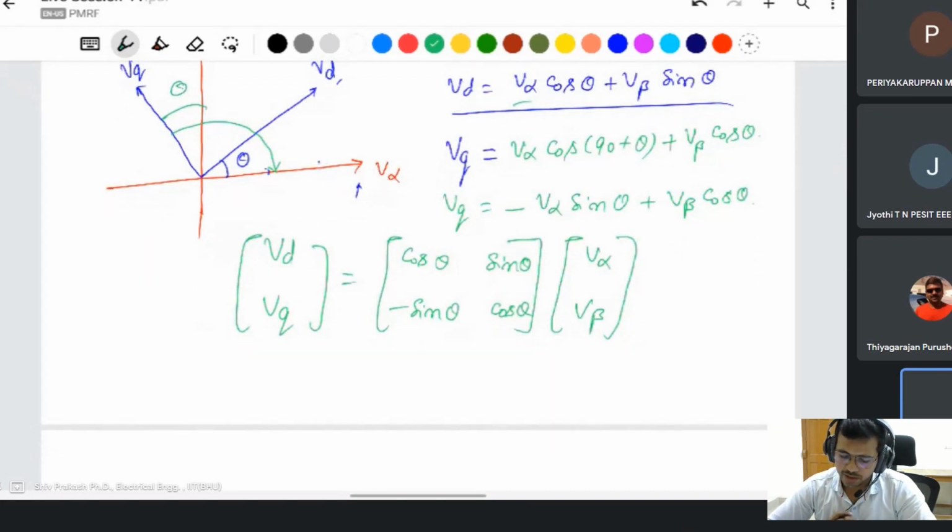That's a simple thing. First convert into V alpha beta. After that you can get Vd and Vq. Simply apply the angle difference only. Take the magnitude and multiply by the cos of the angle between them.